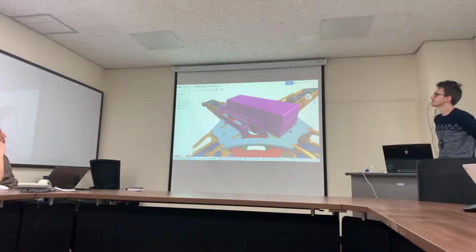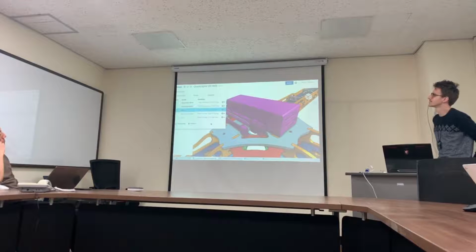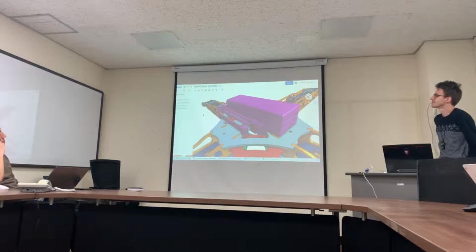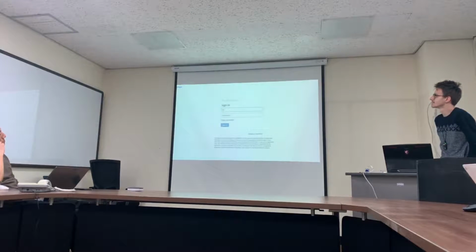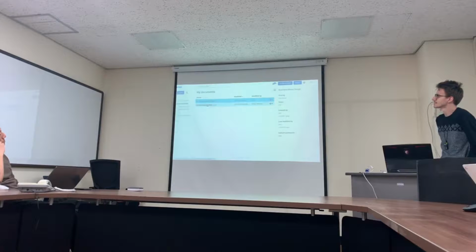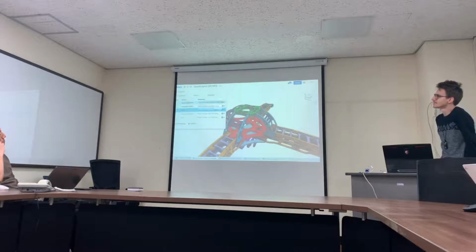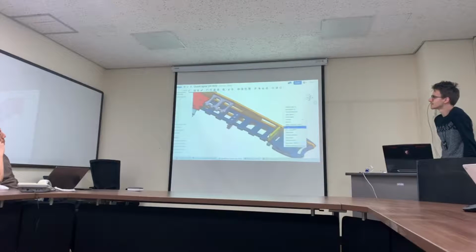Remember, the benefit is the ability for groups to work on the same design independently and to evaluate competing or what-if scenarios. Let's work now, logged in as Don, and make some changes. On the geometry branch, Don would like to add some fillets to the horizontal arm plate.